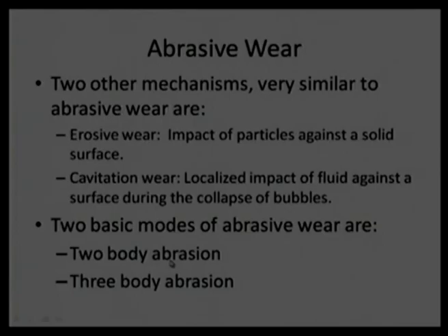Where particle versus asperity interaction happens, we call it third-body or three-body abrasion, assuming the loose particle as a third body. We already have two surfaces, a soft surface and a harder surface, and there will be some particle in between. Naturally, a question arises: is two-body abrasion bad or is three-body abrasion bad? Which should be preferred?